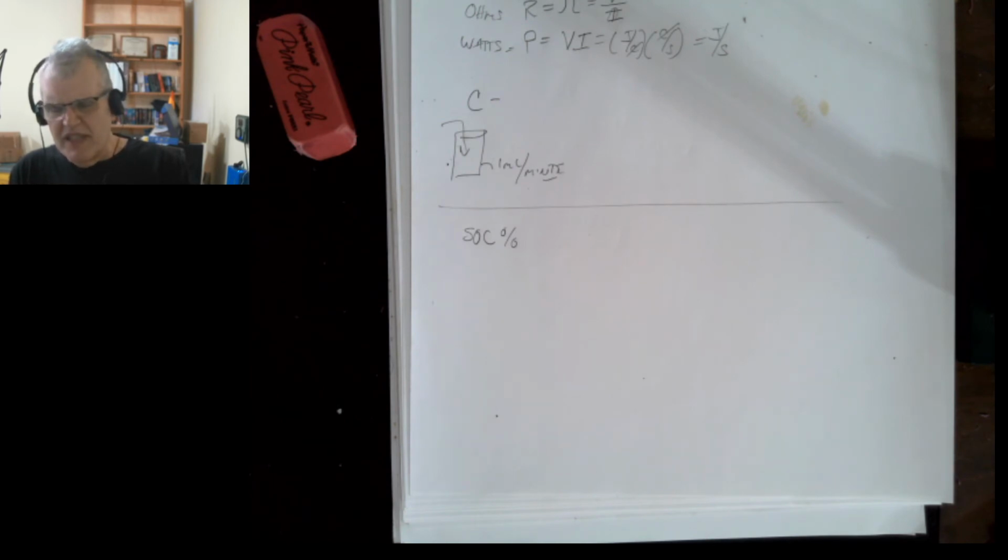The procedure really is, at least for the batteries I'm using, and generally for 18650 batteries: when you first get them out of the pack, you want to measure the internal impedance and the nominal voltage. Actually at that point, since you're not really having a load underneath it, you'd be measuring the open circuit voltage, which gives you an idea of the state of charge. For 18650 batteries, you usually don't want to go below 2.5 volts. For the ones I'm doing, I'm actually using more like 2 volts.